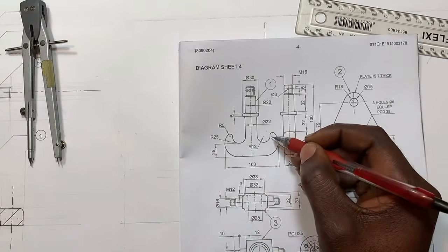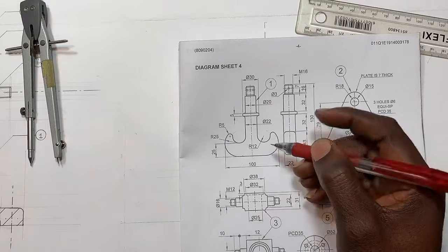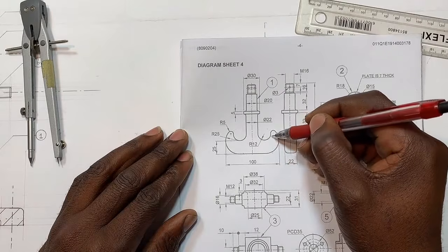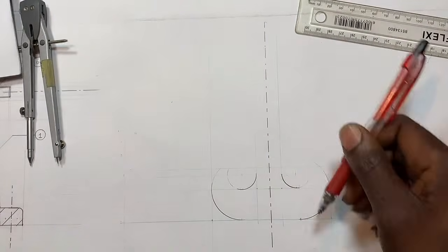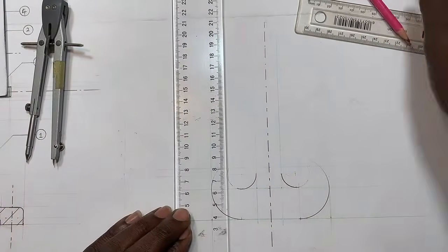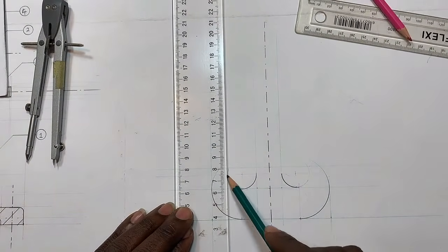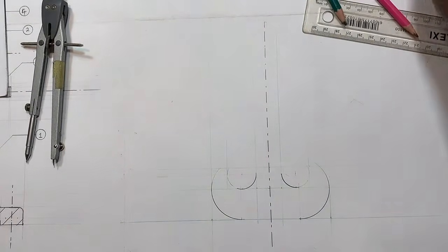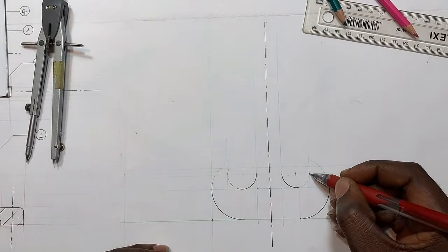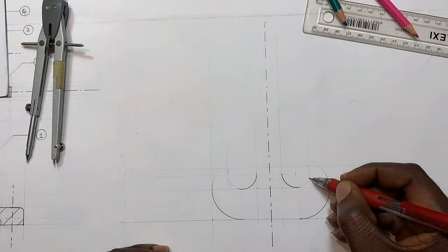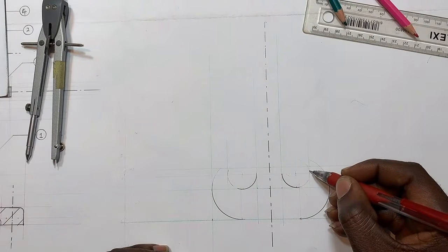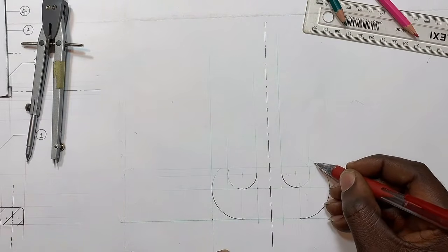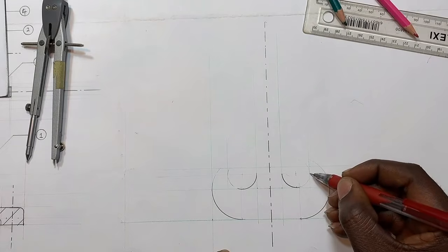So which means we are going to rely on the tangent, if I can call it like that, on the vertical line that is only touching that arc of radius 25. Which is which one? This side, which is going to be this one, this one and that one. We are relying on that, which means I can now draw it dark. There you go. Once I touch this tangent, I can stop there, because I must have another arc or radius that will touch and come in complete with this one, that will touch this tangent of mine.